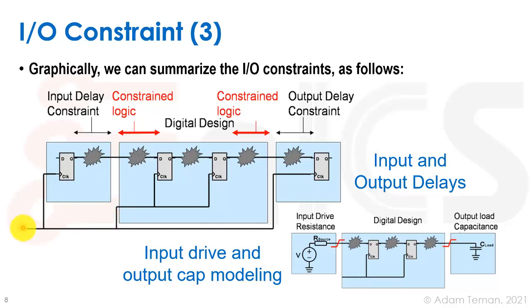If they came from a single clock source, which is a must, because otherwise it would be some sort of asynchronous timing path, then there is some sort of skew between the two. And during synthesis and early stages of design, we treat this skew as 0, and that's fine. But afterwards, once we add clock tree synthesis, this net over here will have some sort of a timing delay.